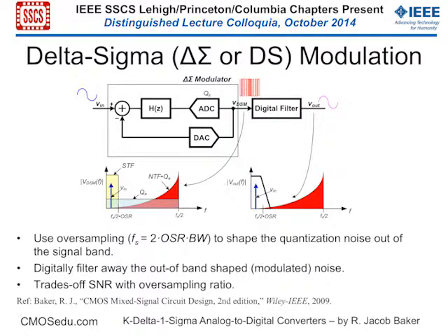So that's what this represents, and then this 1010 thing here, this digital trace, is going into a filter which low-pass filters this. If you're a DSP guy, you could use a simple (1 minus Z to the minus K) over (1 minus Z to the minus 1) moving average filter, just a low-pass sinc response filter, which is what a lot of times people use.